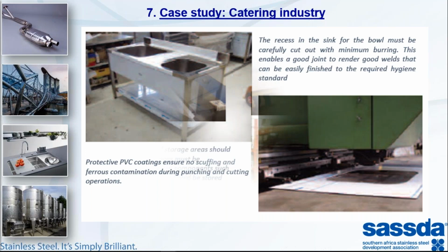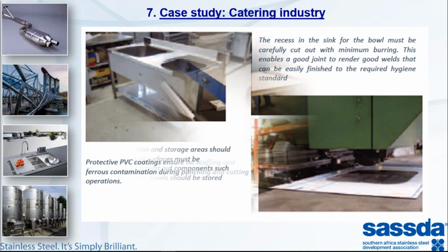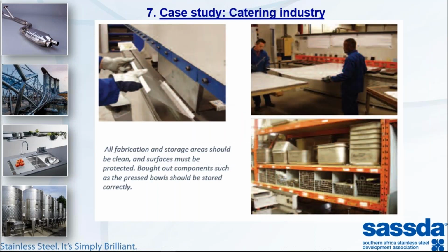On the bending side, the top tool does not create a lot of damage. It's actually the two lines made by the V block at the bottom. So you will keep your PVC at the bottom. There's also a strip that you can put on your V block. We used to call it the bending condom, that you can put on there to protect the material against any friction or abrasion. As you can see at the guillotine, they do the same thing.